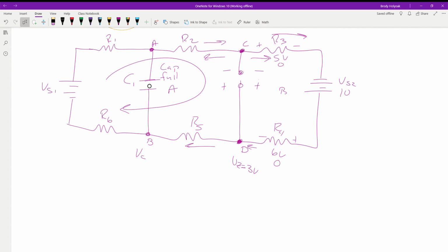When you determine the bias, determine the voltage drop that your diode's going to have. Then you use mesh to solve for the individual currents on those sides. And once you have the currents, you can solve for all the voltages. Basically at this point, it's a two-loop, two-supply problem.